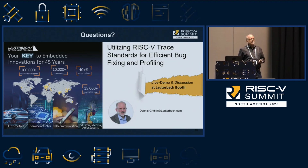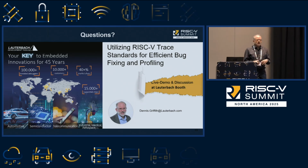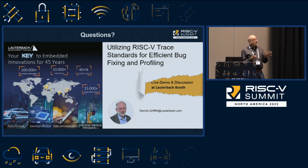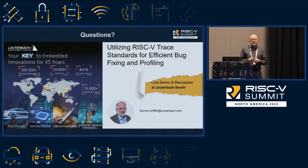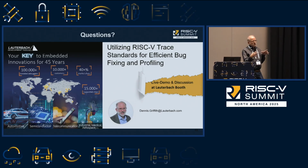Yes. Our tool actually has a mode for this, if I understand the question correctly. You want to know if you can get that trace information in real time? Okay. We have a mode called SPY mode. What happens is that trace comes off the chip and is collected by our tool, and the trace module then becomes a big FIFO.